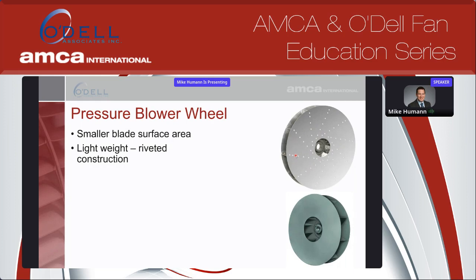Again, you can handle a little bit more, some light dust or some dirtier material, but at the same time, you have that trade-off with efficiency. And these wheels, you can see how narrow they are with long blades, and that's because we're looking to generate pressure while moving lower volumes.